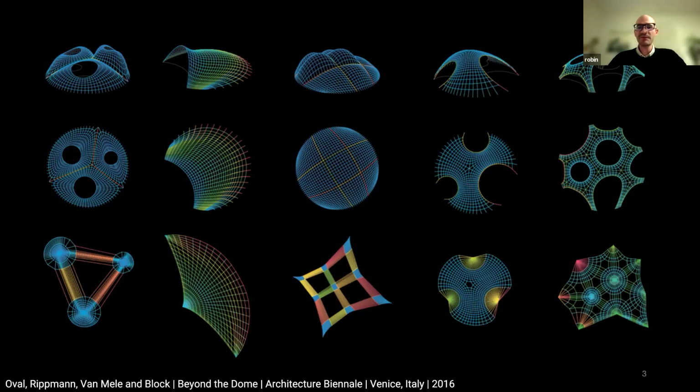And so the geometry of this funicular shape is defined by two things, the two bottom diagrams. So this one, which is like a top view of a force flow, the path of the forces throughout the structure, is a form diagram, and a bottom one is a reciprocal one that shows the distribution of forces within the structure. If you have a look at a couple of features here, with the help of a color map, you can see that the higher forces here along that red boundary, the edge, is related to the equilibrium of this part in red.